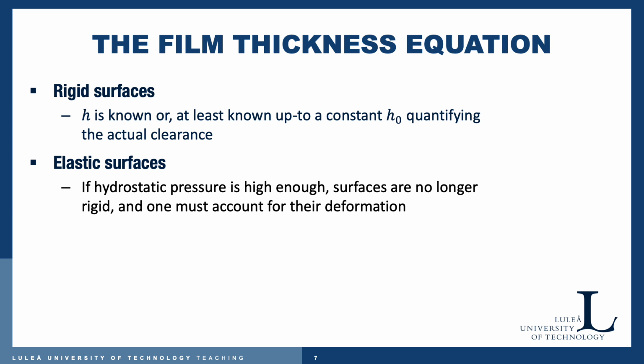If the surfaces may deform, if they are deformable, then the film thickness or clearance will be dependent on the pressure via the deformation. And we can include that into the film thickness equation by adding the deformation as a part of the film thickness description.